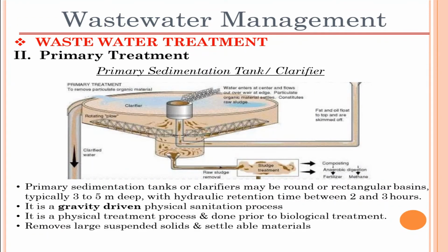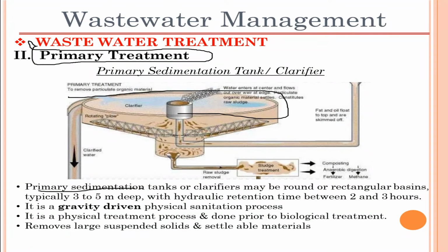Also, we're talking about the second step, which is the primary treatment, the most important treatment of wastewater treatment. Though all of them are important, getting the primary treatment right is the most essential step. It starts with the sedimentation tank. As the water contains some gravel or small rocks after passing through the comminutors in the preliminary process, it moves straight to the sedimentation tank. So the primary treatment starts off in the sedimentation tank.